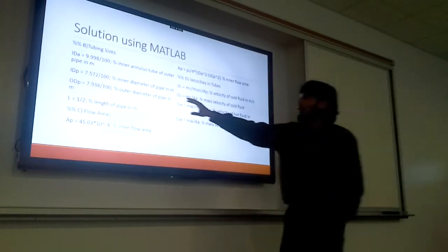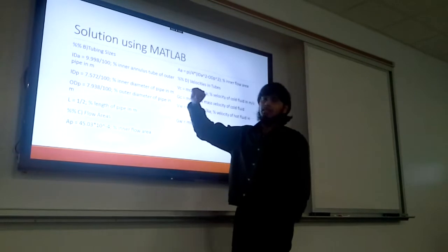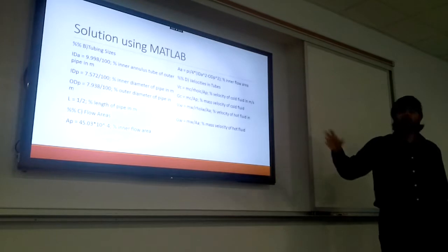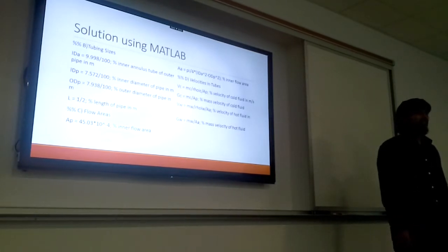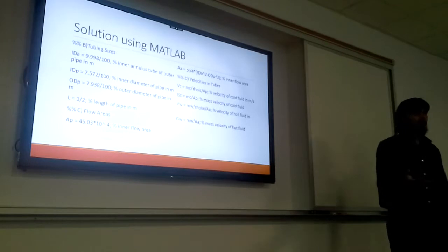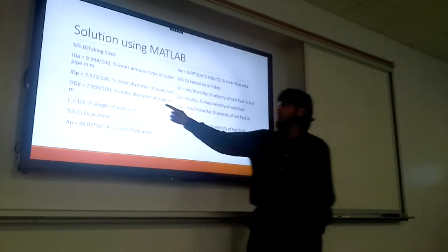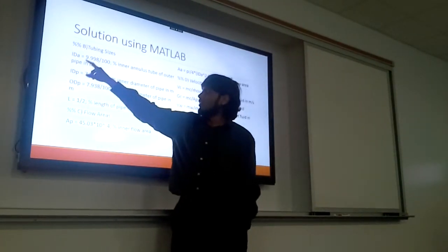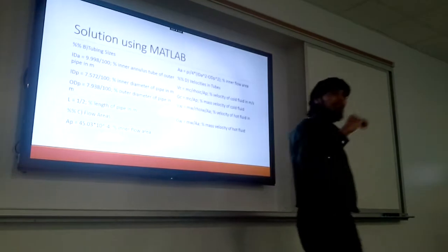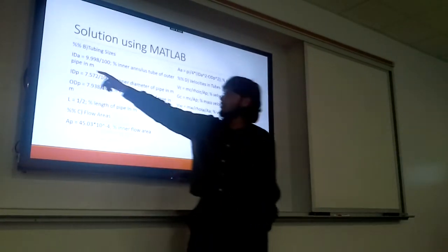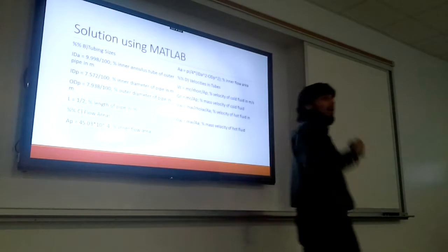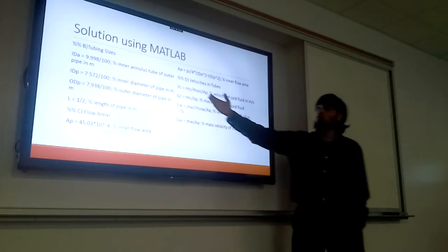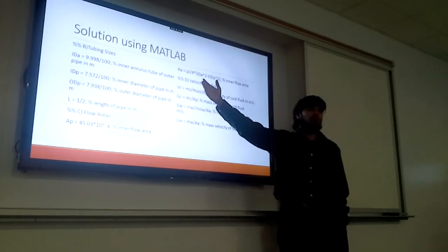In this case, we're using tubes, which are M-type copper tubing of 3 different sizes. All you have to do is look it up in your appendix, I think it's table D.2. Everything's in centimeters, so I convert everything to meters. These two are your inner tubing, and the annulus means basically the outer tubing, so there's space between the outer tubing and the inner tubing. We don't care about the outer diameter of the outer tubing.